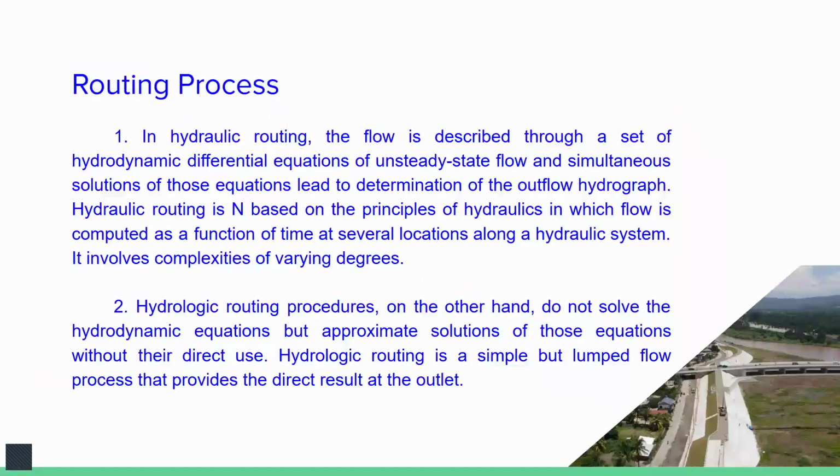So, the routing process. In hydraulic routing, the flow is described through a set of hydrodynamic differential equations of unsteady state flow, and simultaneous solutions of those equations lead to determination of the outflow hydrograph. Hydraulic routing is based on the principles of hydraulics, in which flow is computed as a function of time at several locations along the hydraulic system.